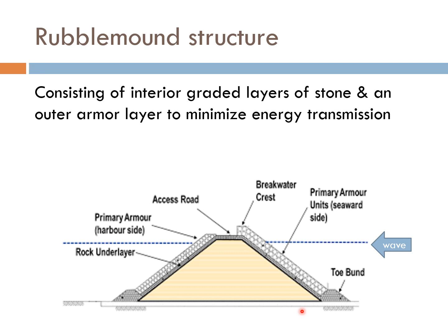The interior of the rubble mound structure is made up of graded stones of different size. Typically, the larger size is on its face so that they are able to withstand the attack of the wave, especially on the sea side, which is most likely going to have larger armor units.